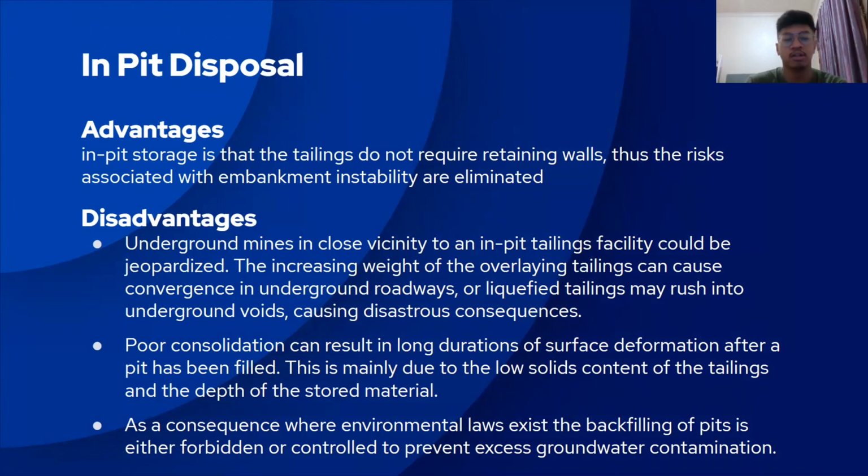Disadvantage first: underground mines in close vicinity to an in-pit. Tailing stability could be jeopardized. The increased weight of the overlying tailing can cause convergence in underground roadways, or liquefied tailing may rise into underground voids, causing disastrous consequences. Poor consideration can result in long duration of surface deformation after a pit is filled. This is mainly due to the low solid content of tailings and depth of the stored material.